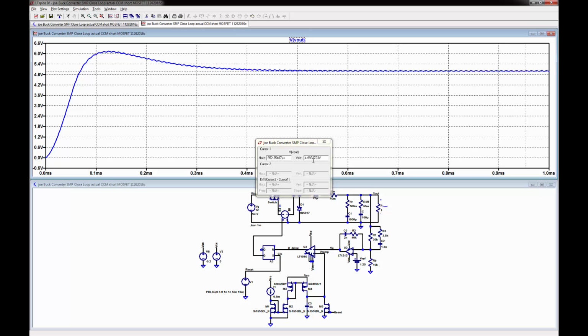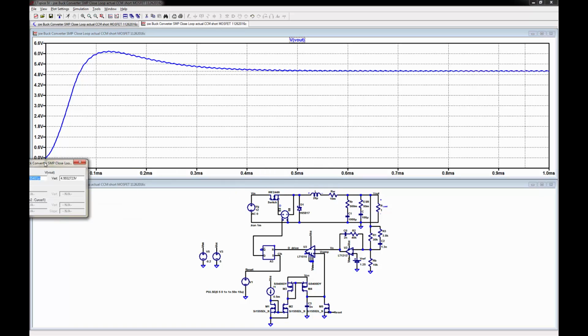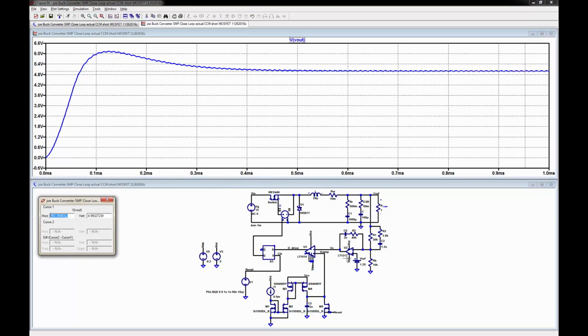You can see the error is less than 7 millivolts. It's 6.8 millivolts or so error, which is very nice. So it shows that, like I said, this is scaled up through this over this, which is 3 plus 1, 4 times 1.25, which is 5 volts, and that's what we got.